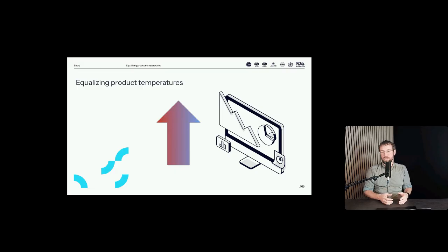You can either use a mapping to confirm that, in this case, the highest quantity that is possible is within the acceptance levels, or the other approach is saying, we know we have these acceptance levels, how much can we fill in before we start to fail? So we would normally always advise, if we're talking smaller units, like fridges and freezers or cold rooms of less than 50 square meters, define what you need and try to see if that can be handled within the acceptance criteria.